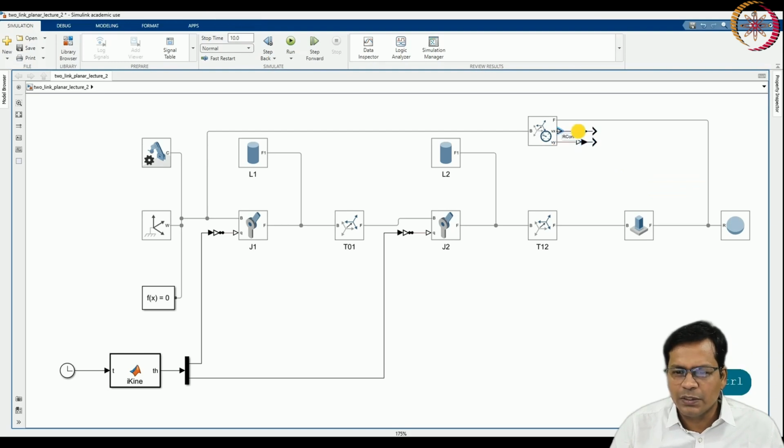These two are Simulink data to physical system blocks that I have used earlier. This time it is otherwise, so you have to convert the physical system data to Simulink data. So this is basically extracting the Vx and Vy, that is the end effector Cartesian velocities along x and along y.